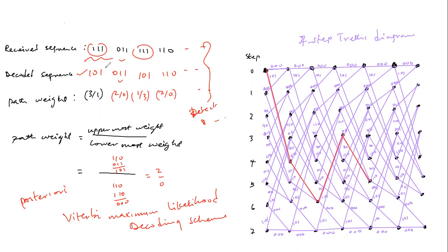The goal of the decoder is to determine the most likely input stream of the encoder, given a knowledge of the encoder characteristics and the received bit stream. The minimum distance between the received sequence and the points representing all possible sequences which could have been produced by the coder in a multi-dimensional space is usually chosen as the correct sequence in the decoding scheme.